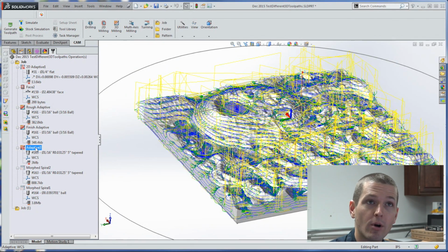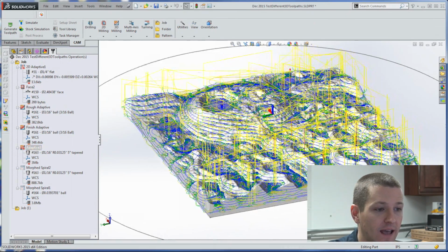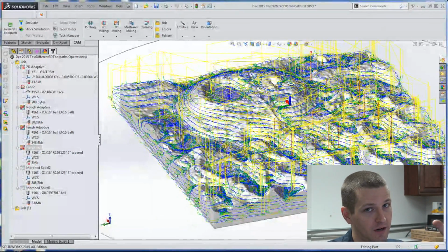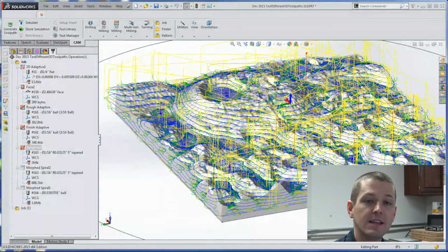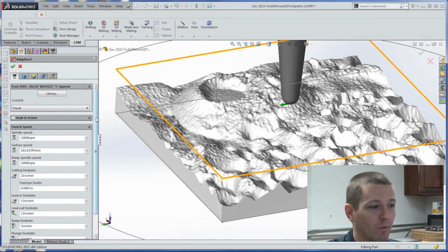We're switching here to a tapered 1/16 inch carbide end mill. We'll use that to come in, and again, we're just trying to remove that material as we get to progressively smaller bits. Now here's a really good question: I like the adaptive roughing strategy because I feel like it helps me ensure I'm not going to plunge that tool into a bunch of uncut material and potentially chip load it or break it or negatively impact surface finish, because we'd have some deflection if we pushed it in too far. So that's the attractive thing. This one though is taking a few minutes to calculate. So I'm okay with that, but it's starting to get to the point where it's inefficient.